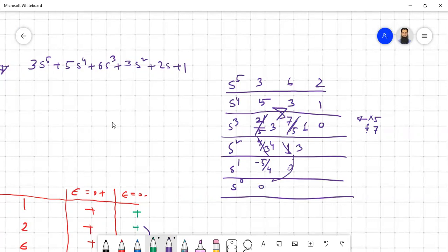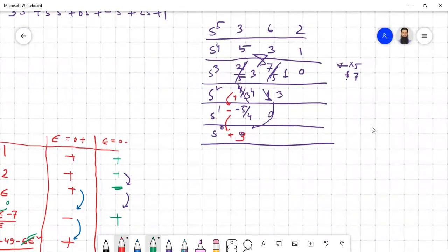Now, if you just observe the sign changes, as you can see, if you reverse the order, still you have two sign changes, from plus to minus, then again from minus to plus. So the result is unchanged. The system is still unstable because of the two poles on the right half plane. So this was your case 1.